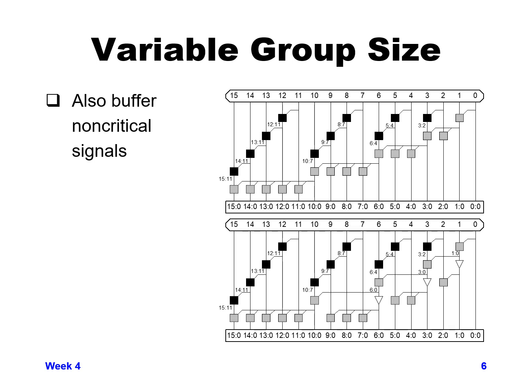So you can see here we only have 2 bits at the beginning, and then we go to bit 3. So we start off, go through a carry generation at bit 1, and then we have 2 bits grouped together, so we jump to bit 3, and then we jump to bit 6, have 3 bits together, and then we lump 4 bits together, and we jump to number 10, and then we lump 5 bits together and jump to 15. And so in this case, you can see there's 1, 2, 3, 4, 5 delay stages instead of the 6 that we had previously.